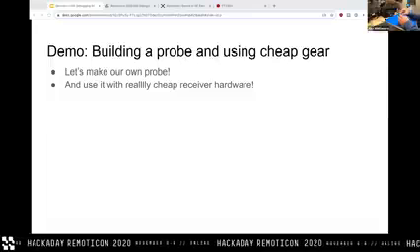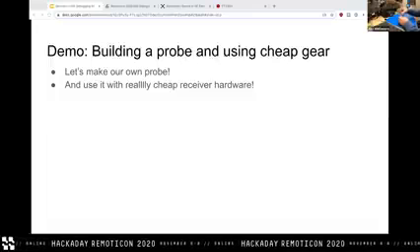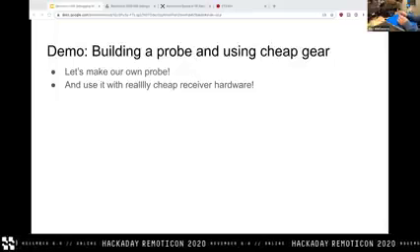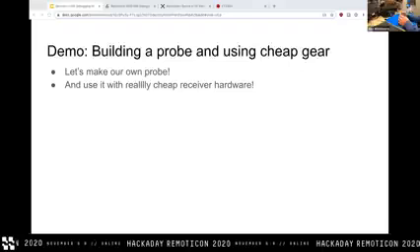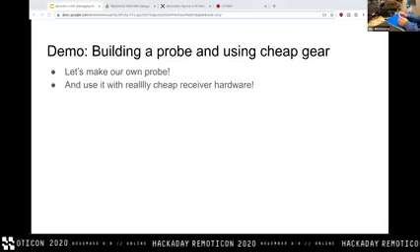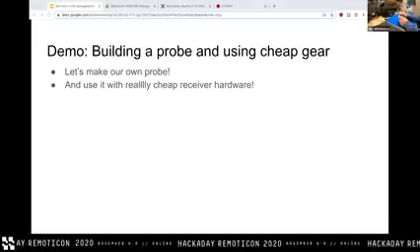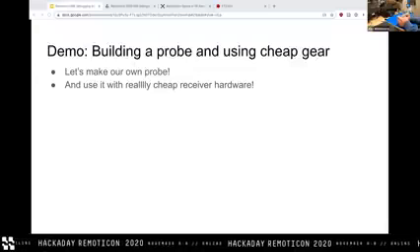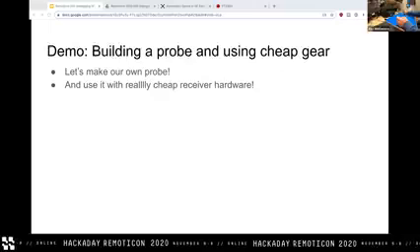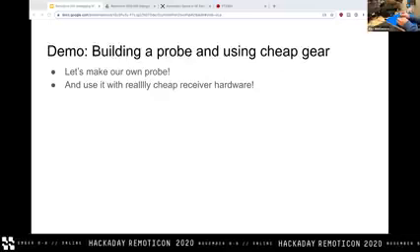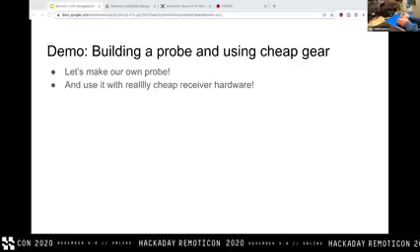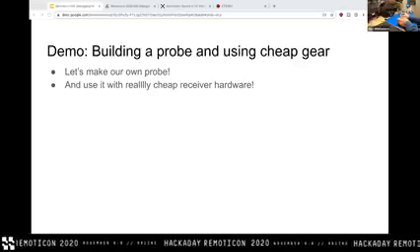So if we plug this guy in, output to the SDR, it will light up with power because the bias T inside the SDR is powering it. Very critical point here is that there's a DC voltage on this pin out of the SDR right now. So what we definitely don't want to do is plug in our probe without the LNA.